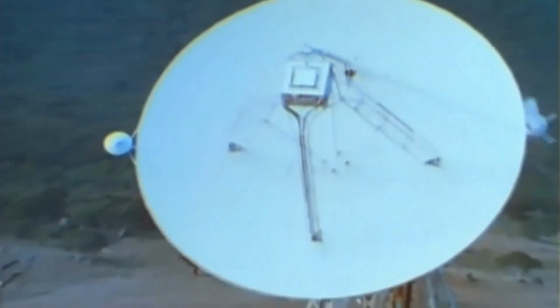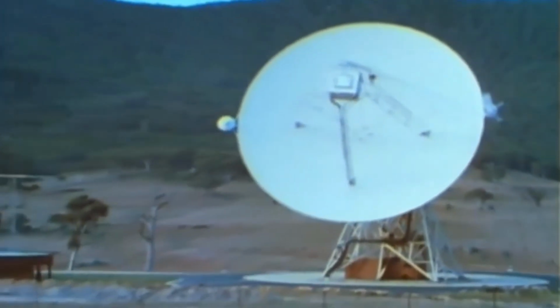The delay in sending commands from the mainframe computer in Houston to onboard AGC is about 1.25 seconds and the same time for the signal to come back. That's a total of 2.5 seconds, which may not seem like much, but in fact it is quite long in the case of an emergency. There would have been a further time delay for Houston's mainframe computers in finding solutions to a specific problem since data was sent up by voice communications, which now translates into minutes. An emergency can spell the end of a mission in seconds."